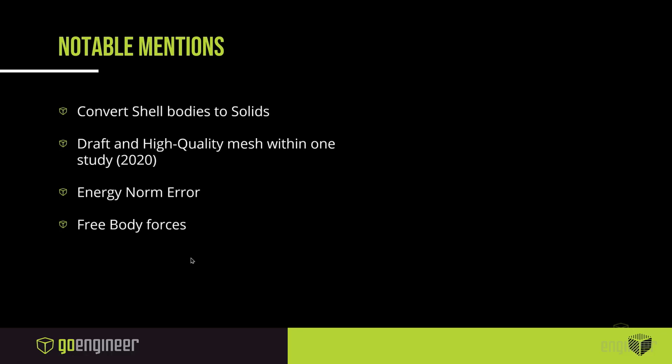And free body forces. I was going to use this for this model, but I ended up fixturing it, so it didn't end up making a difference. But it's a fantastic tool if we don't have any fixtures, or if we don't know where to start with our fixtures. This holds our model together, and it doesn't use the soft springs option, which doesn't add rigidity to our model. It just lets us compute it as a free inertial body, which is also another feature that was really great to mention.